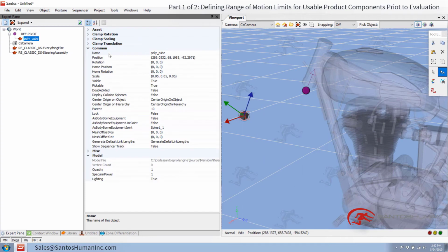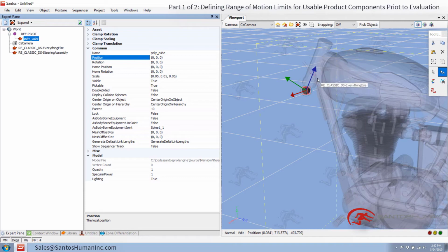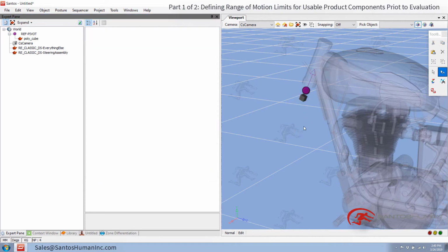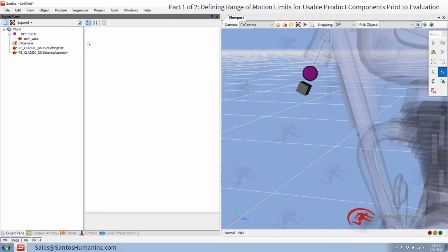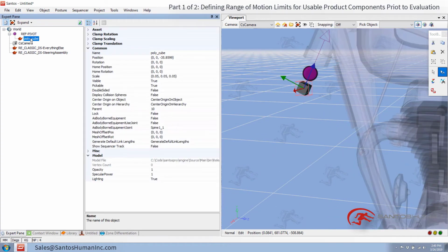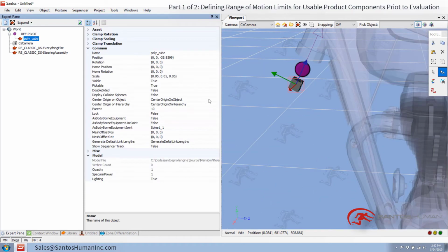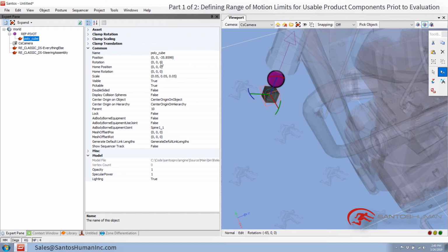So that's that object. If I see its orientation is 0, but its position is different, and that's also referenced to this. So as I get closer, you'll notice that this number is decreasing because it's closer to its parent. If I set it to 0, it coincides directly with its object. But I'm going to put it just a little bit lower so I can get to it. Doesn't matter where it is. I just need the orientation, and the position needs to be along that blue axis or the z-axis of that object. So when I rotate this thing, watch its rotation values. They're relative plus and minus to the parent, so they're really easy to work with now.